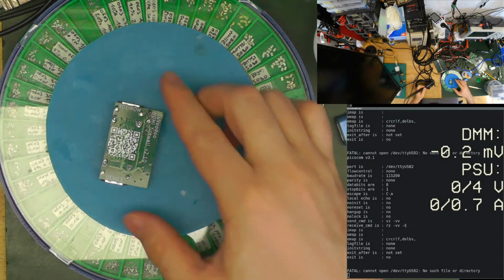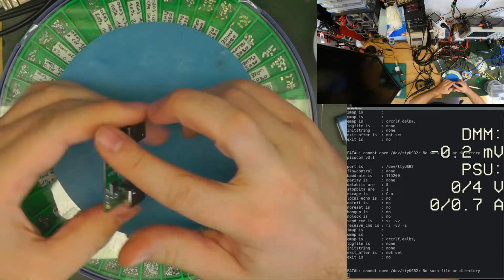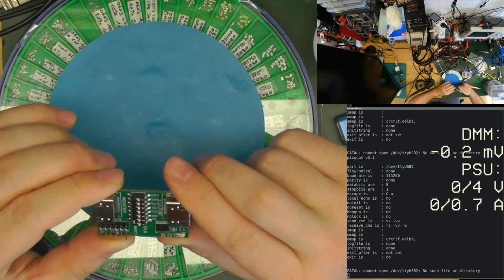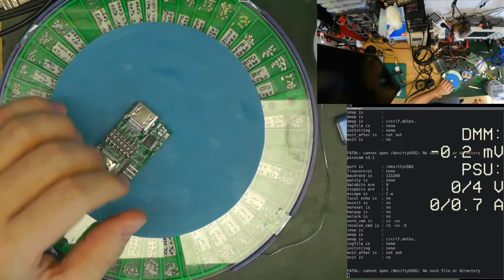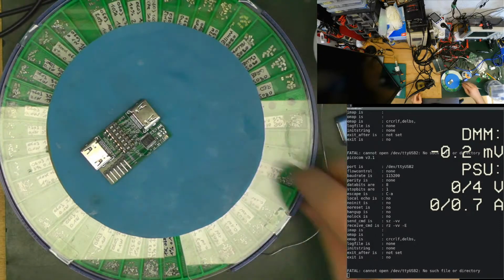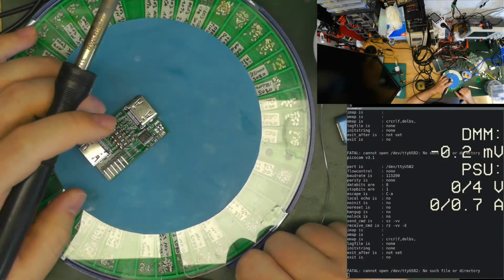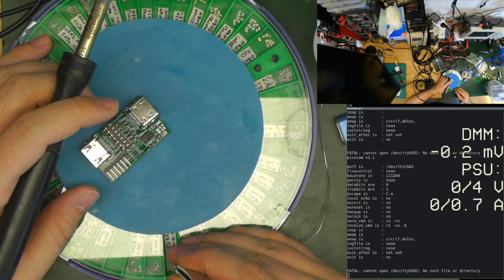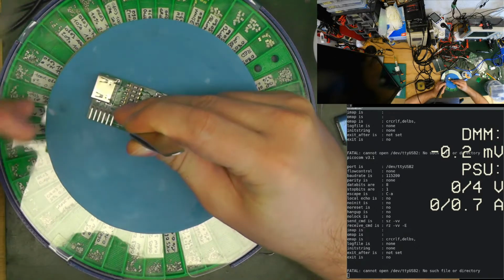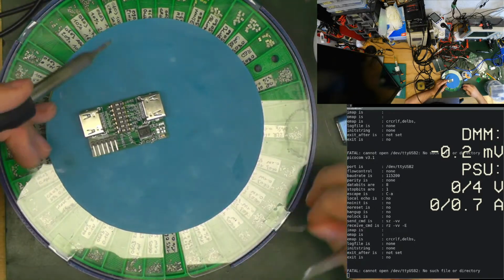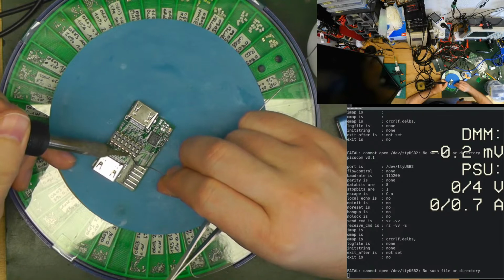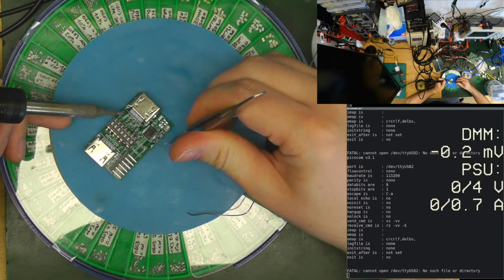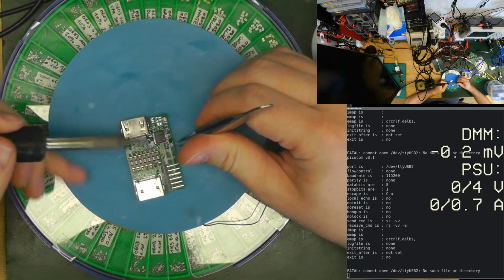Okay. That's done, and then we just need the 2 other pins and the 2 other wires. So we need 1.5k resistors, which are here. 1.5k, 1%. Them, and we need them on the SCL lines. So let's make this solder go up to here. Oh, I can actually solder it this way.